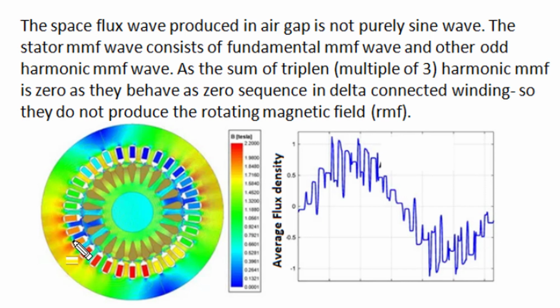At the two pole positions the magnetic flux density has a peak magnitude in one direction and the other direction, as represented by dark brown curves here in this spatial representation. On both sides of the peak position the magnitude gradually and slowly decreases, and in the interpolar region between two poles it has least magnitude, as represented by these dark blue lines.